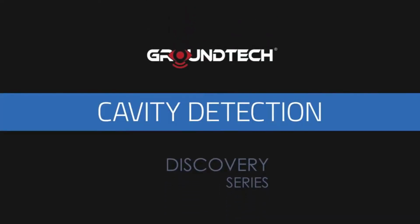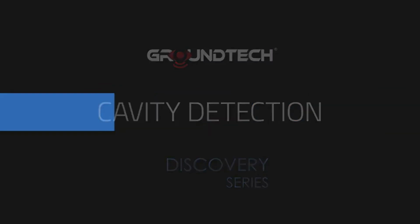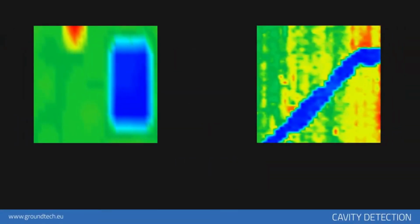Cavity detection. Artificially created underground cavities such as tunnels, chambers, tombs are seen as blue color in the graphic. In the event of any dents or soil filled in the underground, the data will be light blue, turquoise, or light green. What you are searching for must have a distinctive shape and form. For example, if you are searching for a structure that resembles a tomb, the blue area on the graph should be rectangular and the size of a tomb.